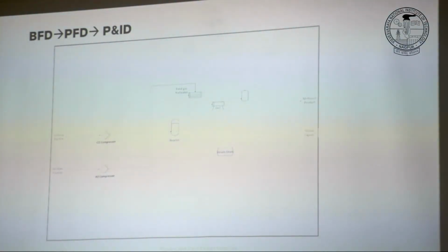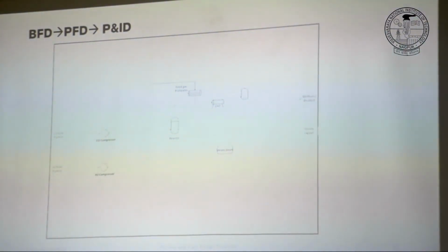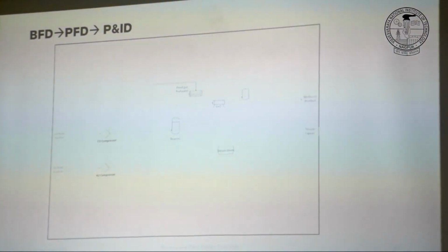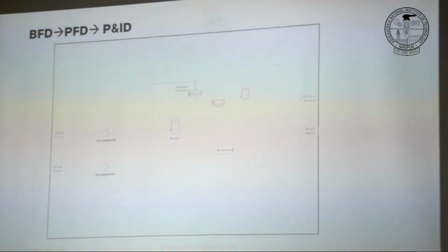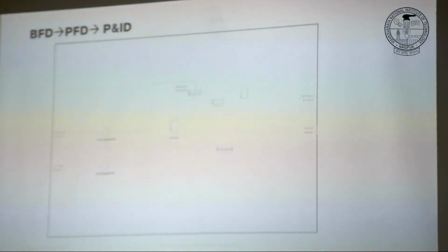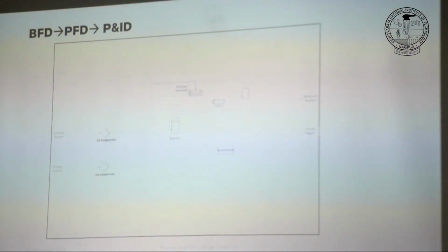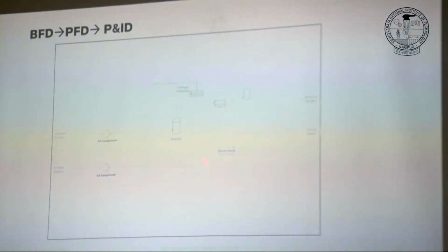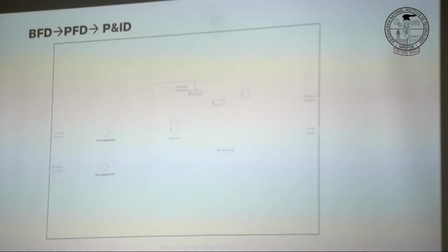We always talk about the temperature difference. But if this stream is coming at 30 degrees at the cold end, the product stream can be at 60 degrees, but since we have to cool it to 30, final cooling will be needed. So this is the U part, the utility. So H, heat integration, we did: steam generation, heating up reactants using product heat. But there is some final heat which must be rejected to the atmosphere by utility cooling, so that's this U part.